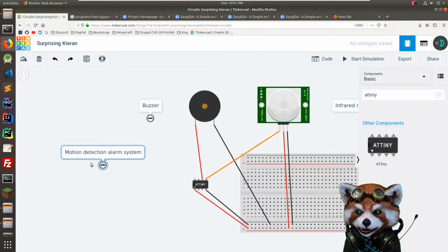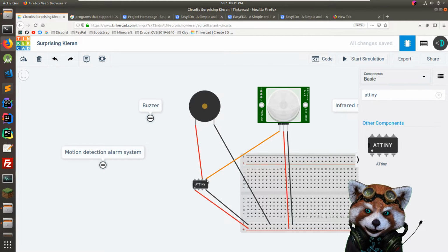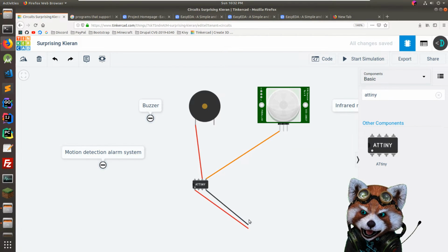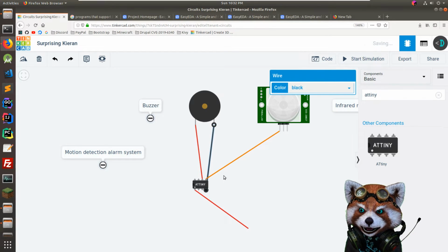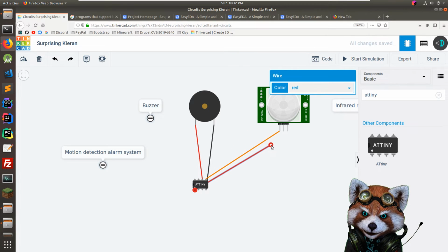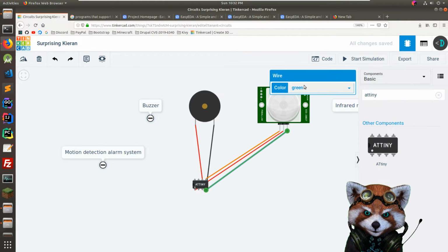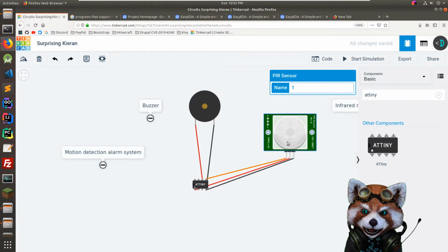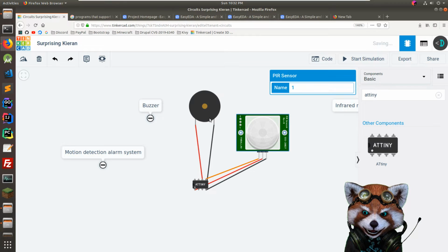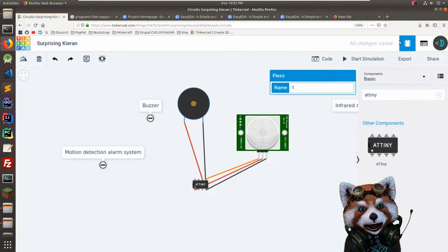So now we don't have the big, bulky Arduino powering this whole thing. And in fact, we could, at this point, even eliminate the whole breadboard and wire up these things directly like this. And so power would go there, and then another ground would go there. So you could even do it like that. Yep. So there's like a minimal